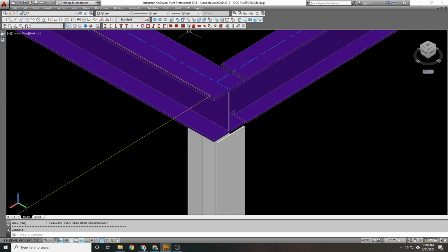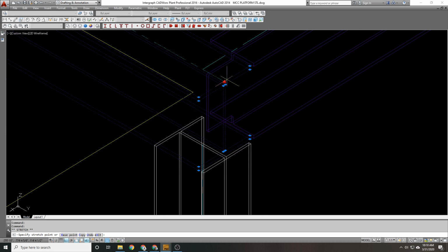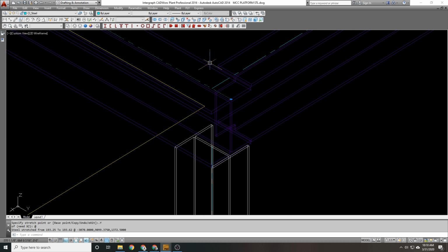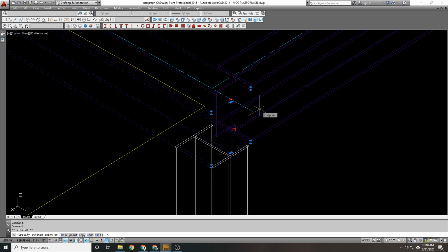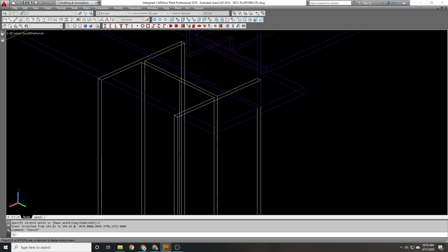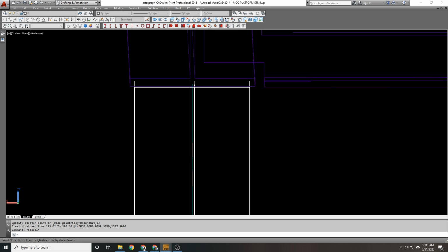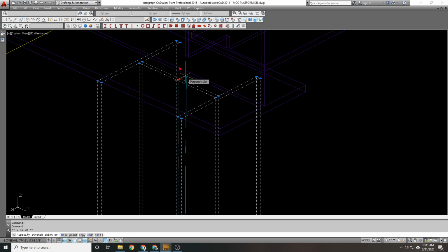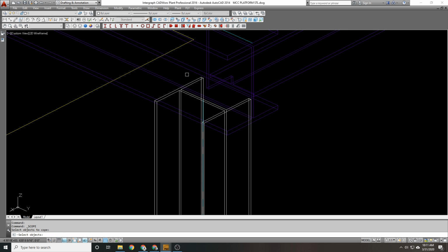It makes it wider than my 615. So what I'm going to do here is bring this a little bit further past. So I'm going to say .y to the outside edge of this column, and then I'm going to bring this a little further out. We're actually bolting. So because we're bolting, this is going to have to come out 3 inches, not half an inch. I'm going to use a cap plate on this. I was going to say we should be just wider than this thing, and I don't know why this didn't come to the bottom of this, but we're going to do that now. There we go. Okay, so now we're going to use a cap plate.